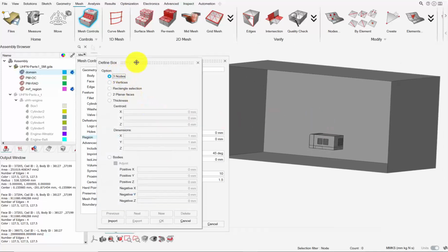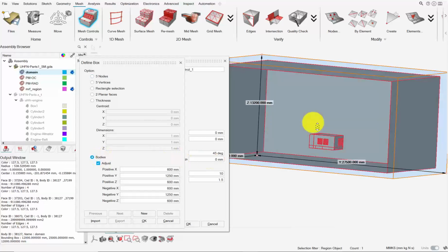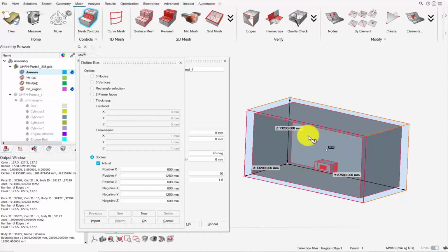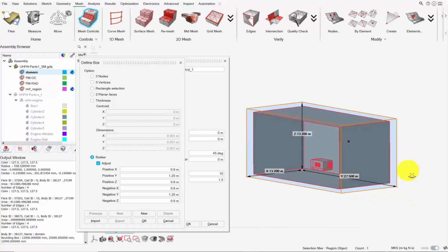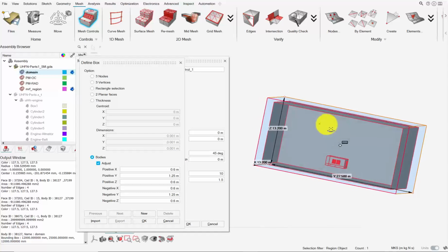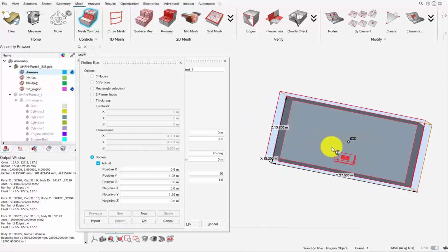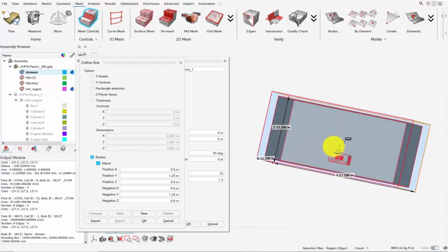It's going to be a cuboid. We'll define it using a body. Let's change the dimension to meter so that it's easier to resize the refinement zone. I want to position the refinement zone so that it's right in the middle of all 4 dimensions to the region of interest.